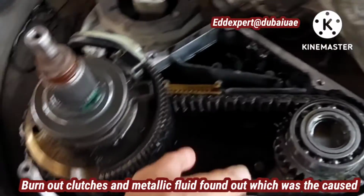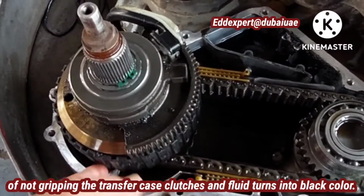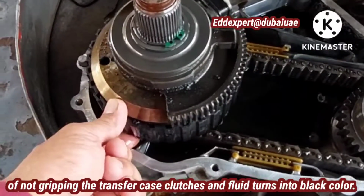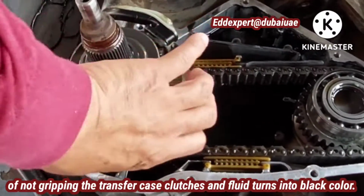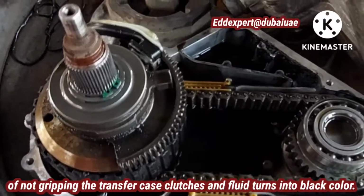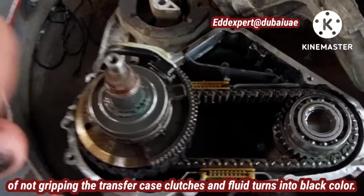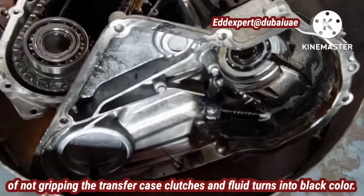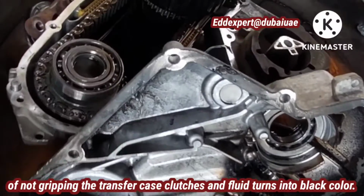The color of the transfer case shows that these are burnt clutches, and these are the clutches inside. It doesn't squeeze the four-wheel drive, so that's why it's causing a problem on the four-wheel drive. It shows here also the sign of burning clutches.